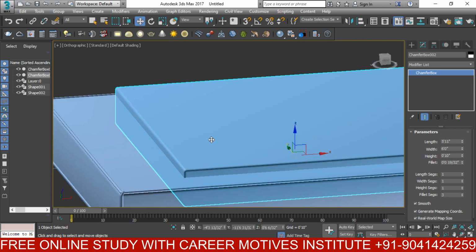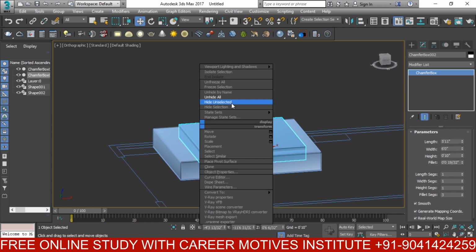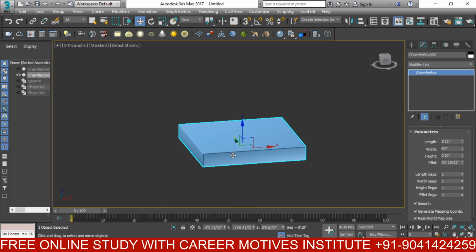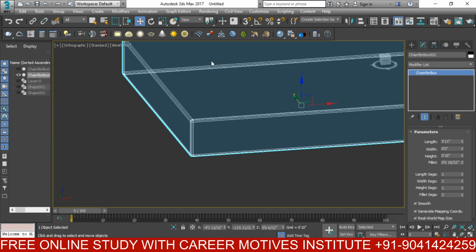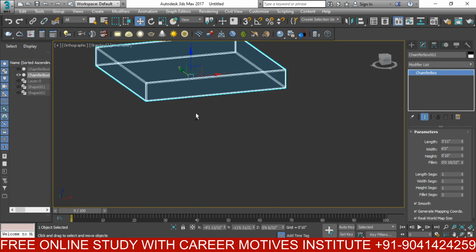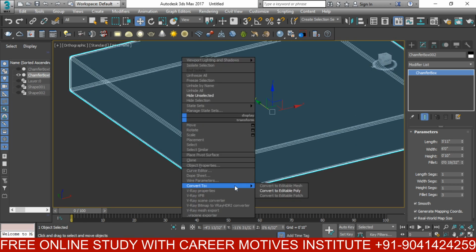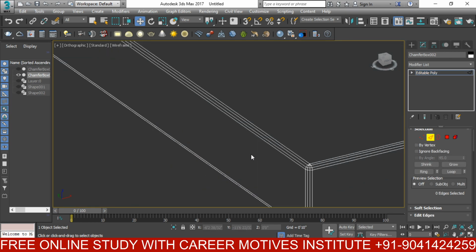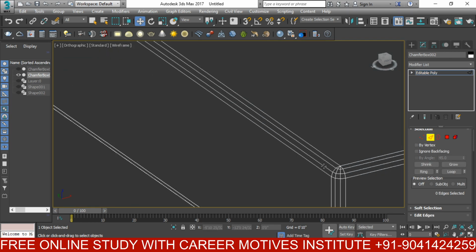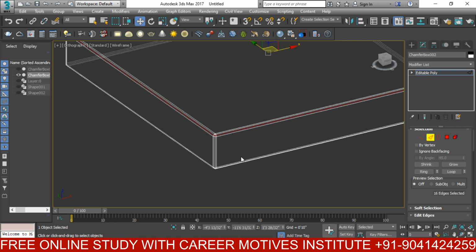Now as I want to modify the mattress only, I have selected hide unselected, and now I'm going to modify this mattress. Right click, convert to editable poly. First of all, I'm selecting edge, I'm selecting this portion, then loop.